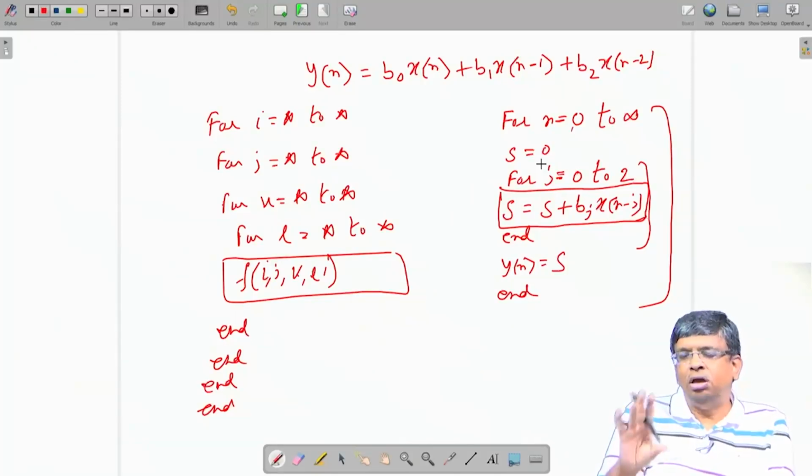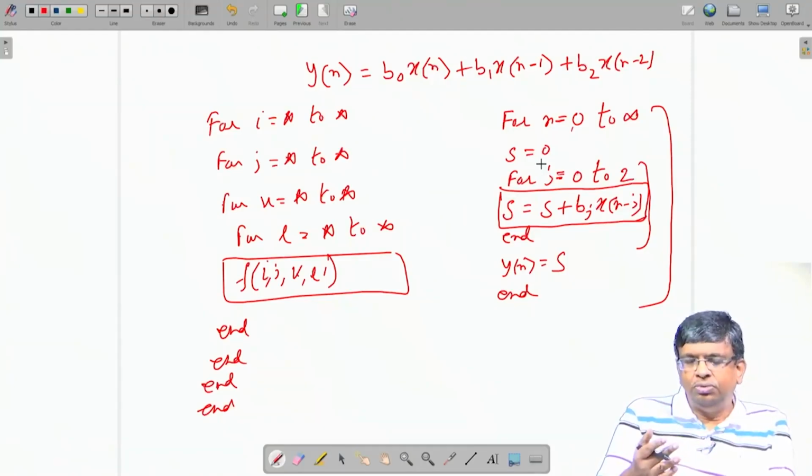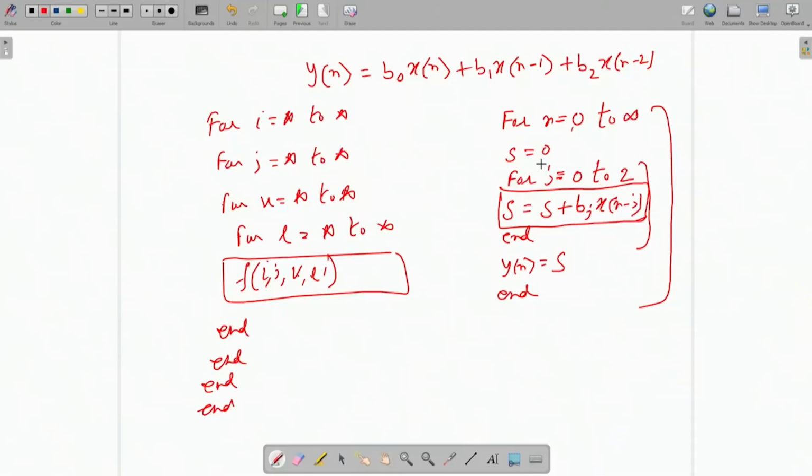So you cannot realize a 4-dimensional DG on an IC or a 5-dimensional DG on an IC. Then what we do is we map a higher dimensional DG to a lower dimensional DG. Lower dimension can be 3 or 2 or 1. That mapping is called systolic transformation, which we could consider later if time permits. By that systolic transformation we map a high dimensional DG to a lower dimensional DG, so that the lower dimensional DG is realizable because its dimension is 3, 2 or 1. That is the entire philosophy of array architecture design.